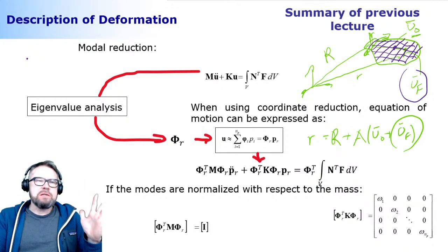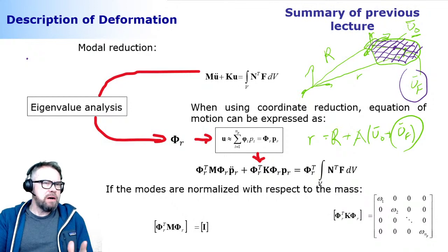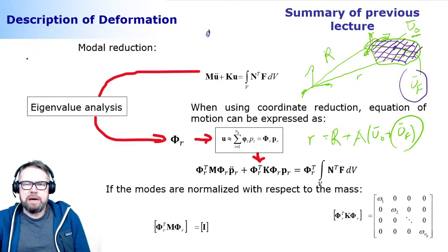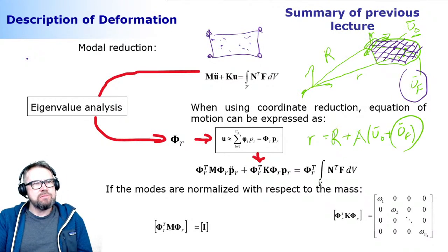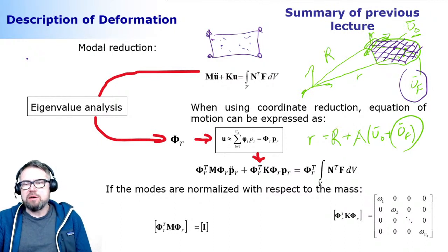Okay, we do have information about every single particle, because if we go back to the single element here, this is a plate element. Every particle within the boundaries of this element can be described with the help of a shape function. The shape function tells you how the particles are assumed to follow a certain deformation. What deformation particularly? The deformation associated with the nodal degrees of freedom.